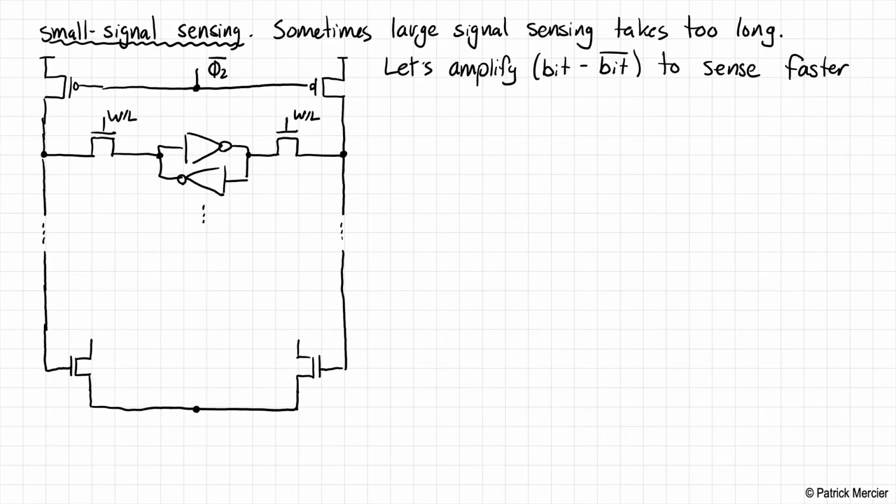Digital circuits, anyways, are made up of analog parts. So we have some sort of tail current source, although in this case, we're not going to bias it as a current source. We're going to do something a little different. We'll get into what that transistor actually does in a moment, but for now, I want to finish the rest of this design.